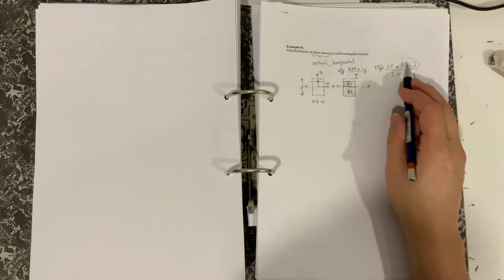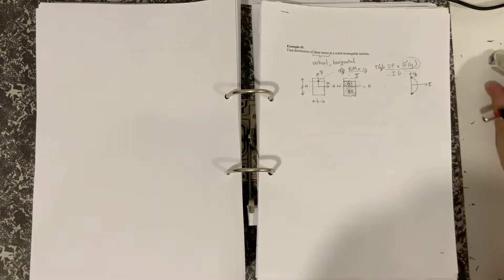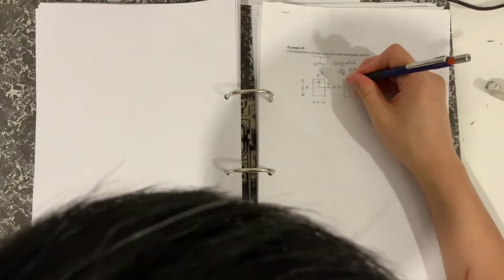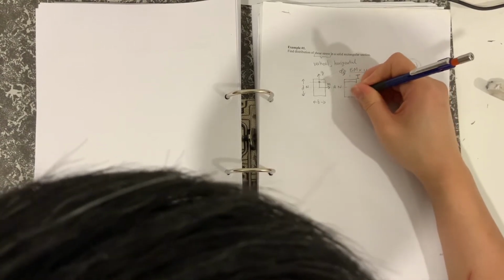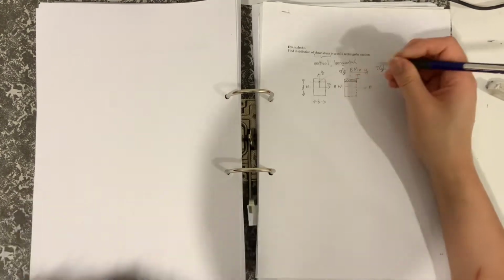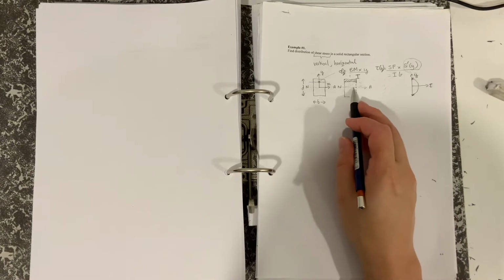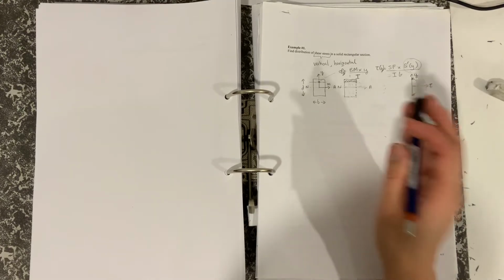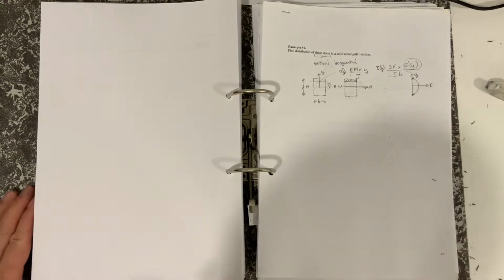Then again, you're working out your S dash, and it would work out to give exactly the same numerical value had we done it that way. Okay. So obviously this way is easier because all of the shaded area is above or below the neutral axis. All right, so I'll just mention that as one of the subtleties of the equation.